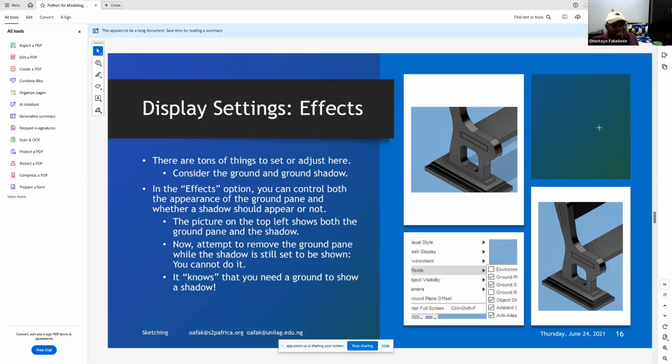It understands physics. It knows that if you drop something, it will go down. So if your z-axis is up, and you leave an object at the z-axis when you are doing the simulation, it may be acted upon by gravity and it will fall down. So that will come in the simulation direction. That's why it is important for you to decide where is your up and where is not your up.